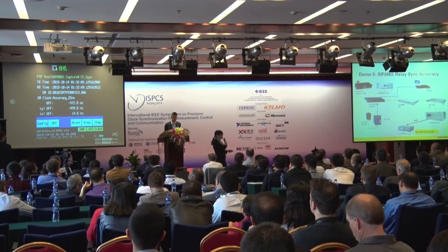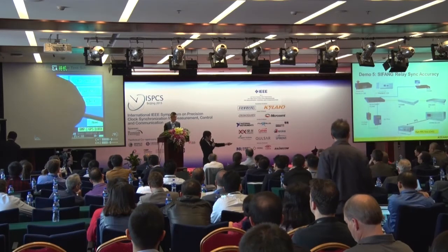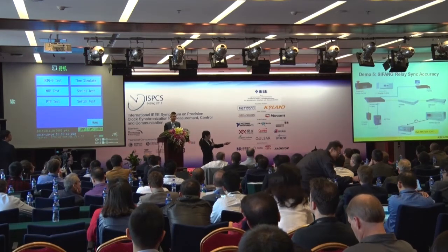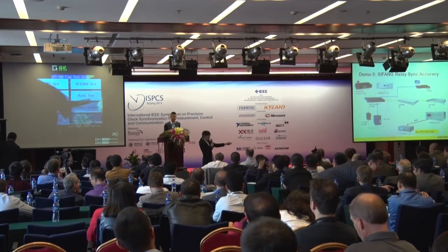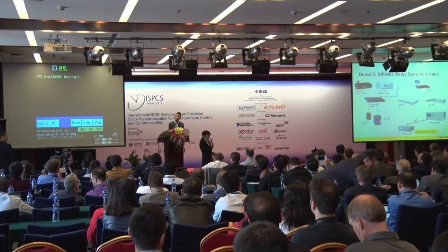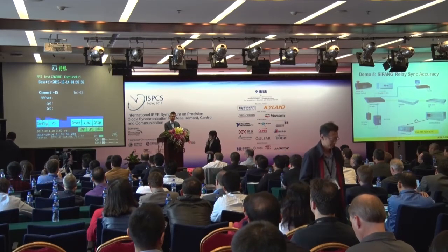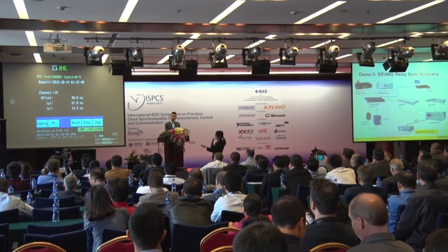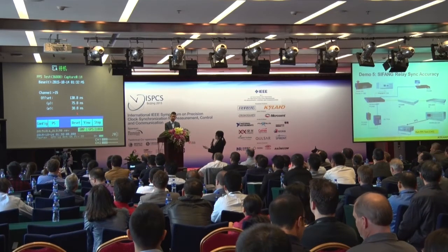So we have two different end devices here. One is the Sifang protection relay. This one is synced with direct IEEE1588, but it also has a PPS output. So we can check the PPS output sync accuracy through this one to check how the Sifang relay is actually synced with IEEE1588. On the screen, this shows the PPS output of the Sifang relay after the time synchronization using IEEE1588.